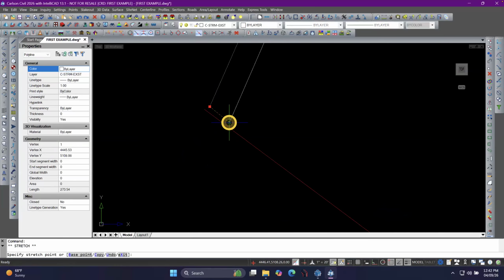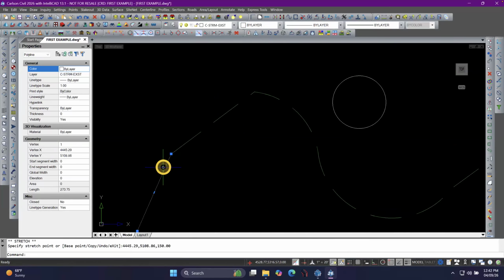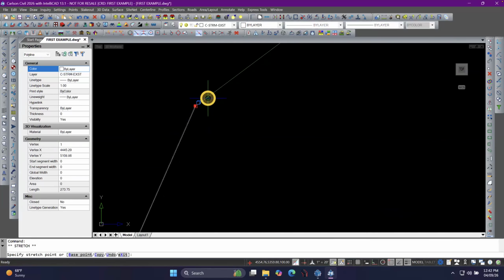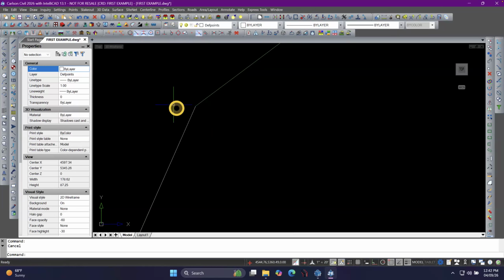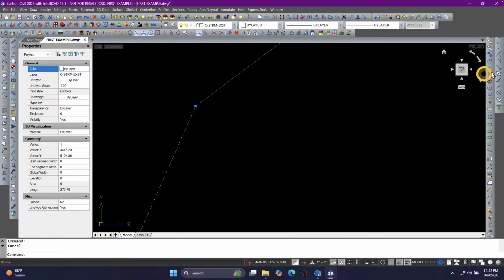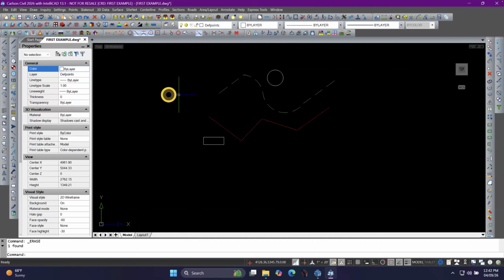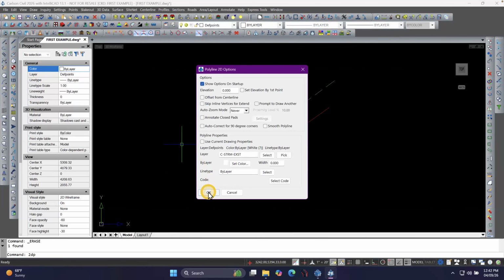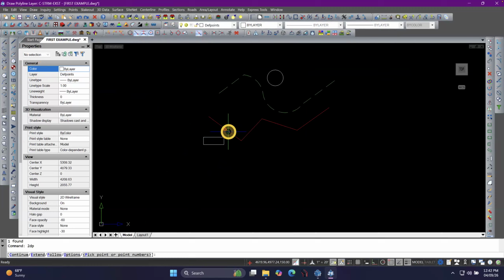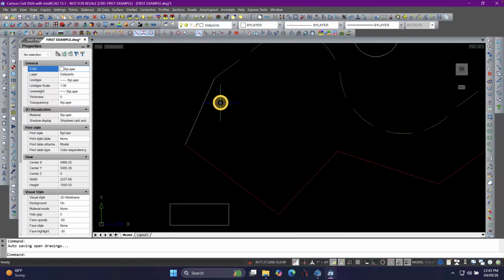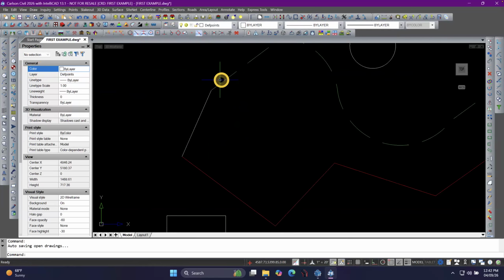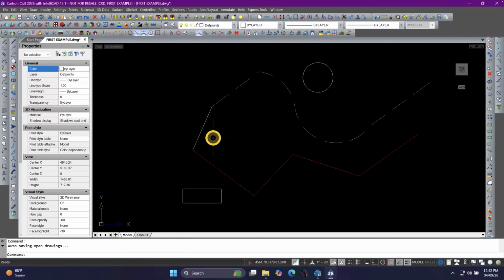I'm going to take that and I'm going to just hover over this red line. See how it snaps to that endpoint? And I'll do that same thing, go from here. And now it's connected. Okay, so we're going to talk about all those kind of tools and those snaps. And in fact, now with my snapping turned on, now when I draw that line, all I have to do is point near the end. See, it's picking up midpoint, endpoint. So the end of that line and the end of that line, and it snaps to those particular points. That's very important when you're doing this stuff, because certain lines have to be connected for them to work correctly.